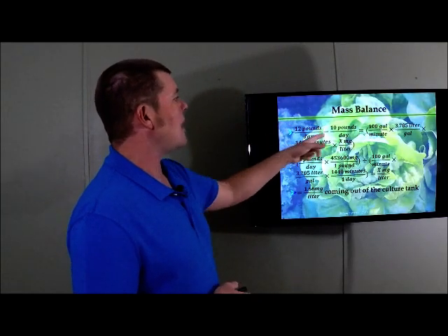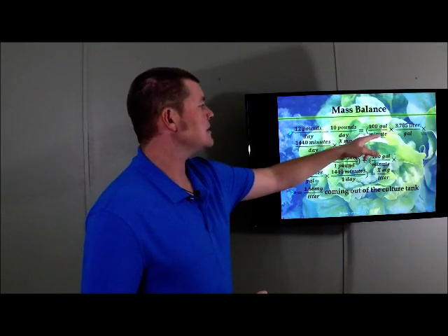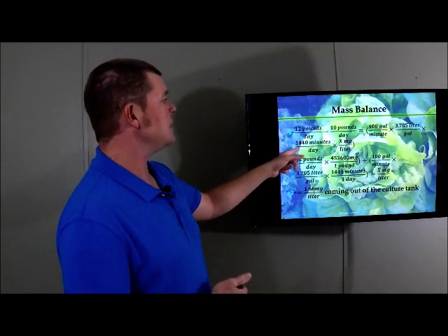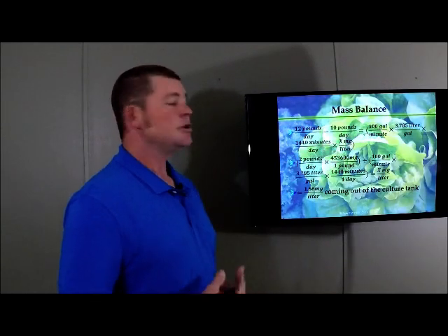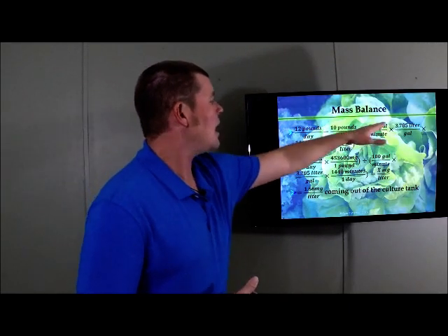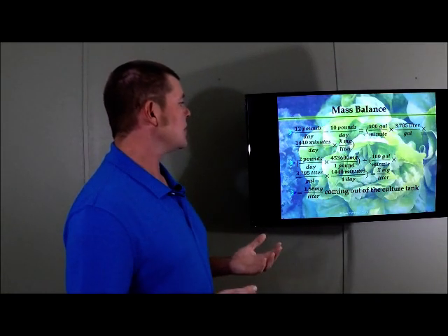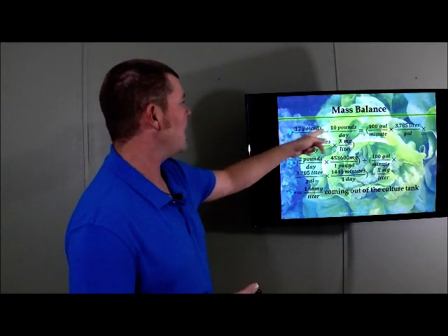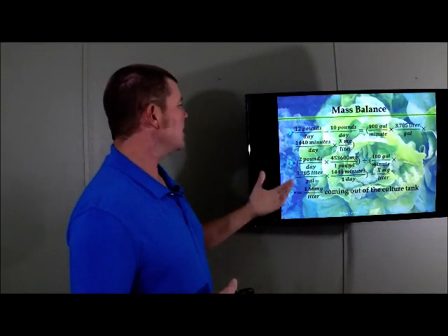12 pounds per day minus 10 pounds per day equals 100 gallons per minute times 3.785 liters per gallon times 1,440 minutes per day times X milligrams per liter. So again, we're trying to get this into terms where we can cancel out some of these common units, gallons, liters, etc., so that we can come up with a final answer here. Once we move on from this equation, 12 pounds minus 10 pounds a day, 2 pounds a day, then we do our multiplication here and we get our answer.